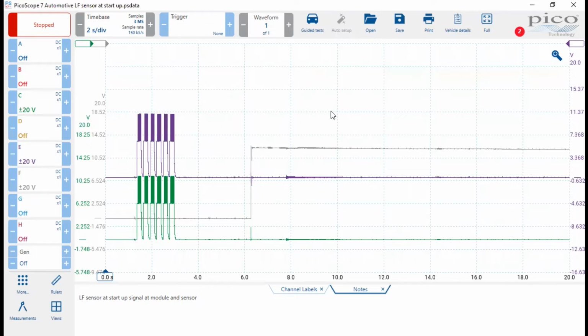So now I need to reevaluate, if you will, exactly how the computer is determining whether this thing's okay or not. And literally, the computer has no way to test the resistance of the circuit. So there's really only two things it can look at. One of them being voltage, which is the most common thing that's monitored or measured by a computer to determine status of the circuit. But the only other thing I can think of here would be current.